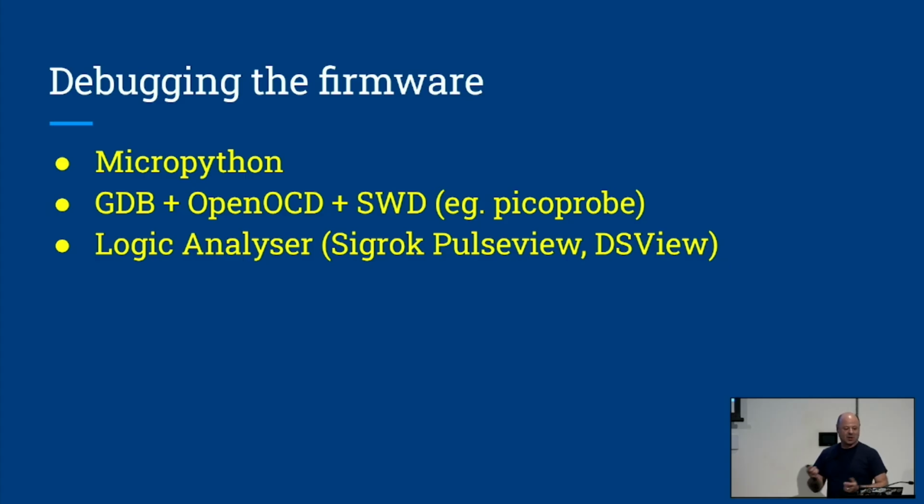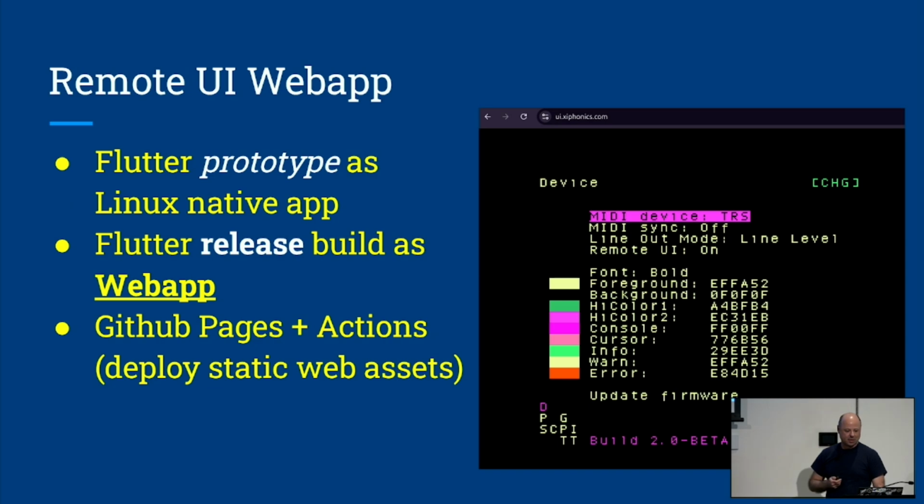You just have to live with these things, but sometimes it's not fun living with them. I've also put the logic analyzer here, even though I'm talking about firmware, because like I said, sometimes I found that the only way to debug a software problem is actually using a logic analyzer and looking at the signals coming out of the hardware, versus trying to just use the debugger in your code.